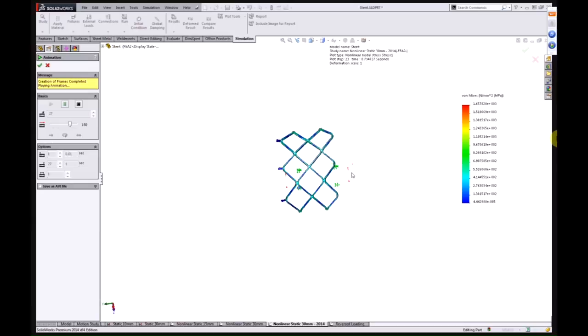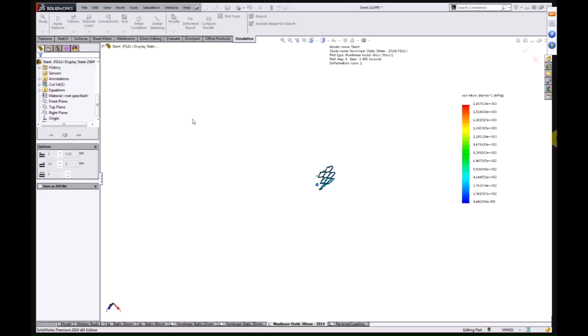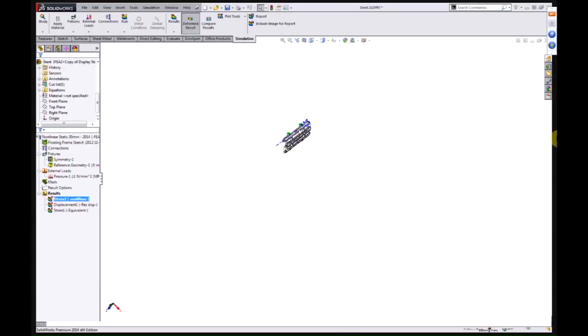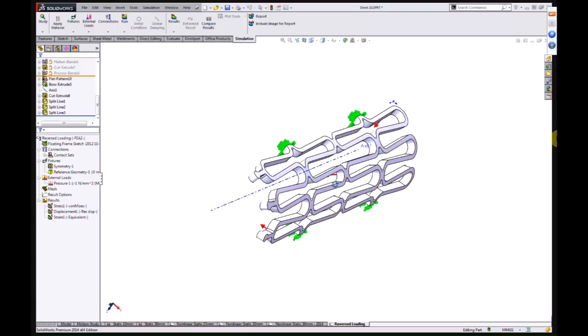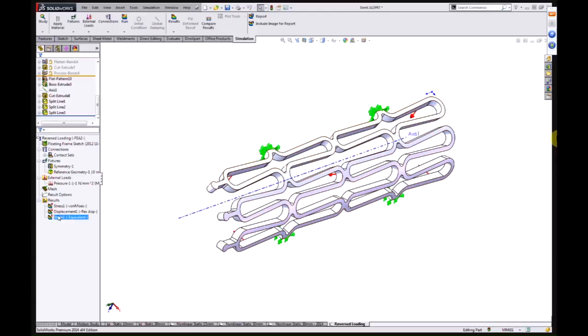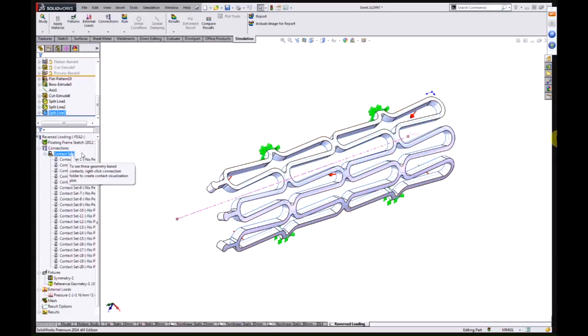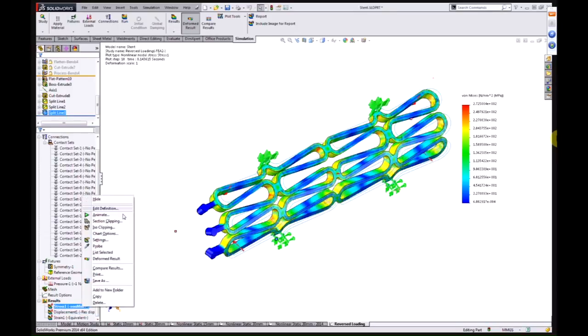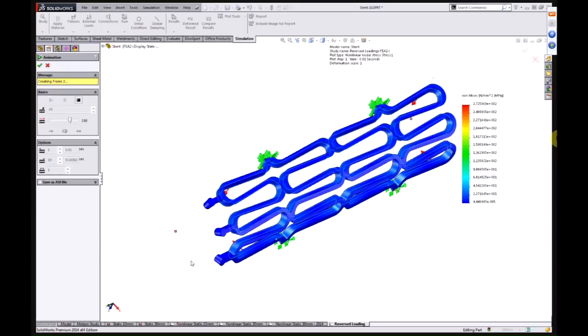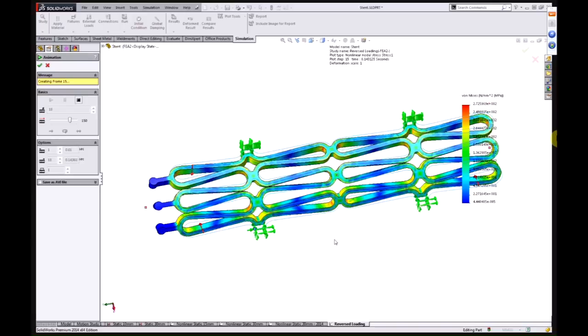Or if we try to compress the shape, pull it inwards, we very quickly get to a point where the arms start to rub together, and we resolve that with contact interactions between all the faces that may meet. Once we start getting into contact modeling, things get a little tougher for us in SOLIDWORKS Simulation Premium. If we compress the thing, we get to the point where the parts come together. We can resolve a little bit further, but ultimately the degree of deformation we can see going inwards is a lot smaller. This is in the ballpark of the limit of what we've been able to achieve.